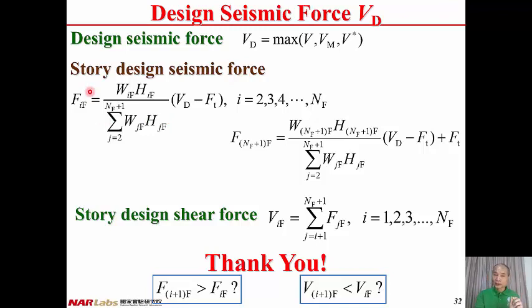Fi^F is the design seismic force of the i floor, and is proportional to the weight of the floor and also the elevation of the floor. Then we have the equation here other than the roof, and here is the equation for the determination of roof design seismic force. Once we have the design seismic force of all the stories, then we can have design shear force, Vi^F.